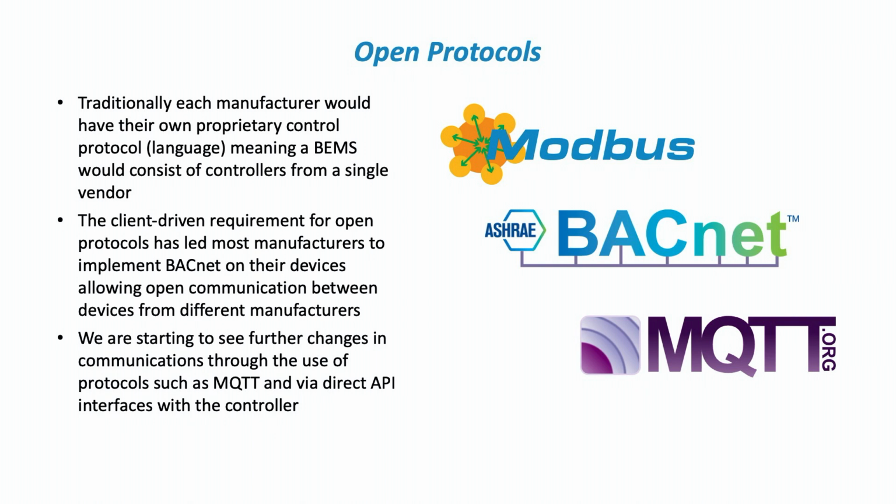You have to meet certain criteria set out by ASHRAE in order for your device to be BACnet compliant. There is a myth that if it doesn't bear the BTL mark, which is the BACnet Testing Laboratory mark, that it is not a true BACnet device. That is actually not true. BTL assures that it meets the BACnet standard, but you do not have to bear the BTL mark in order to be able to make and sell a BACnet device. You have to be compliant with the standard, but you do not have to bear the BTL mark in order to show that compliance. You can do your own testing.